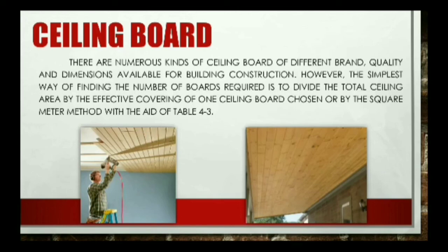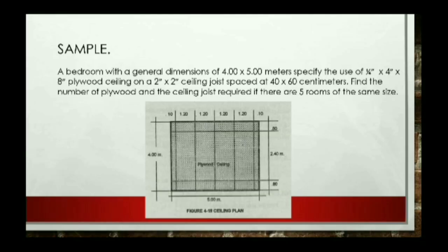So, a sample problem. A bedroom with the general dimensions of 4 by 5 meters specifies the use of 1/4 inch by 4 inches by 8 inches plywood ceiling on a 2 inches by 2 inches ceiling joist spaced at 40 by 60 centimeters. Find the number of plywood and the ceiling joist required if there are 5 rooms of the same size. The solution is